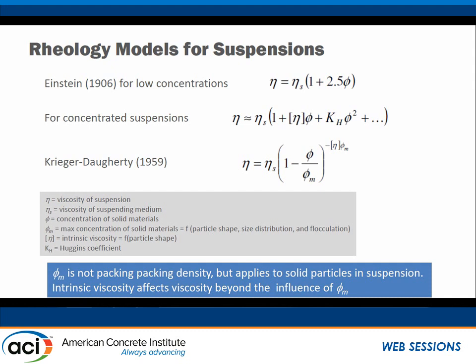So that's to get your packing, but what we really want to know from a concrete standpoint is the viscosity. And there are a number of equations for concrete. The challenge with concrete is that it's a highly concentrated suspension. And so the models that are out there that you'll see generally are for much lower concentrations. And the Krieger-Dougherty one is a good one to use for illustration purposes. So basically it's the viscosity of the concrete as a function of the viscosity of the suspending medium, which would be paste. And then you have the packing of the solid particles relative to the maximum packing.